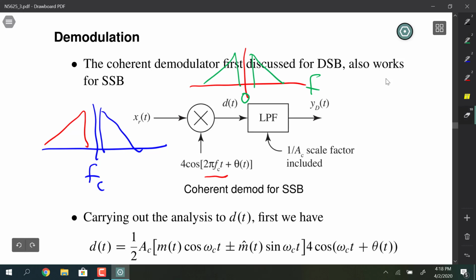But the issue with needing the bandpass filter is you're going to be receiving an upper single sideband signal, and in this project you've got another channel sitting right there. If you don't block that from getting in, it will think that it's double sideband and bring that guy right in too, and you'll end up with this happening.